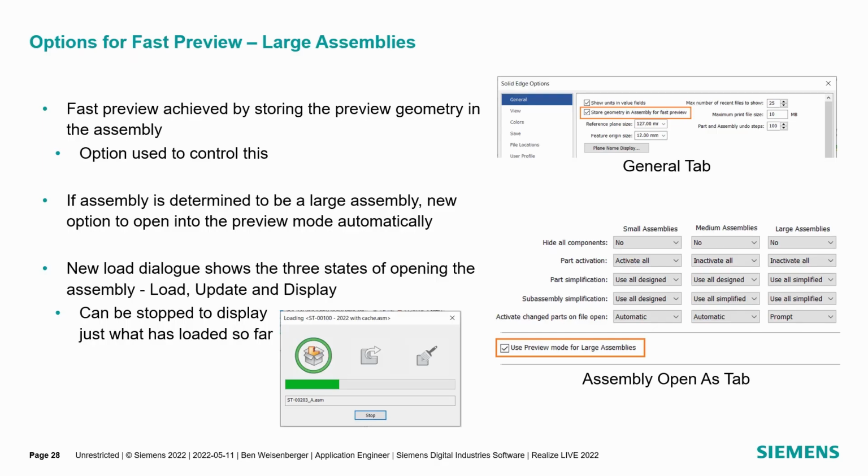What we saw there was that when opening the assembly, due to its size, it opened very quickly into the preview environment. In here, we're able to easily change the scope of what to ultimately load by hiding and showing parts, either graphically or through display configuration. And then once we're happy, we can simply choose to edit the assembly. The benefit being that since we've reduced the number of visible parts, the assembly that we wanted to work on was open much, much faster.